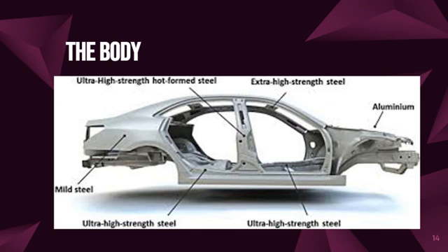Many heavy vehicles now use subframes of simple construction to which the engine and gearbox are attached already. The subframe is supported on the main frame and is fixed on it through some suitable rubber connections to isolate the engine vibrations. Due to the development in spot welding and sheet pressing techniques, most of the vehicles have integral construction. All the assembly units of the vehicles are attached to the body, which also acts as the frame.